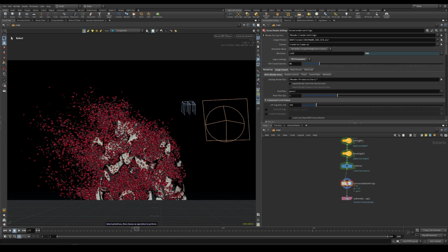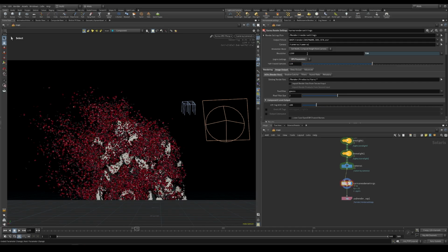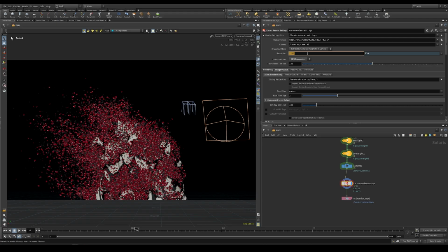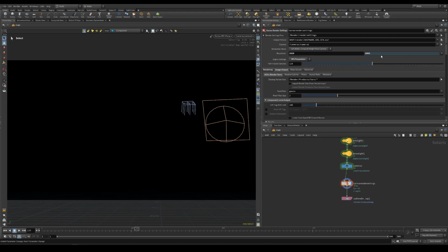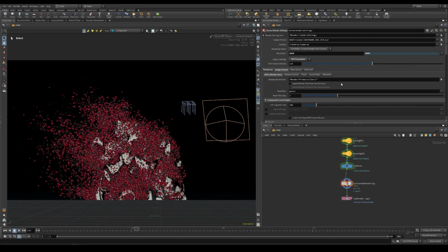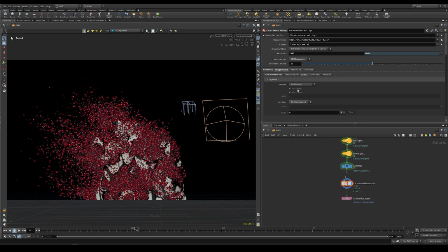So for the setting, let's see, I want to set this path trace sample to 128. Here I want to output a full HD, so 1920, and the height will be computed by default. We don't want any denoise, we will apply the denoise in the compositing area. And for the output, we want to write it to the job variable render and if name.